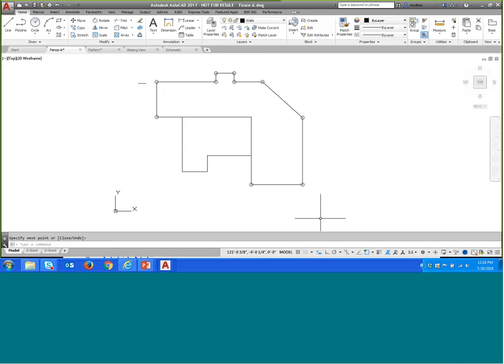Now let's draw the roof using the midpoint. So I'll select the line command again, and then point it closer to the midpoint of this line. And now I have to draw it perpendicular to the side of the house wall here, to show the roof line.